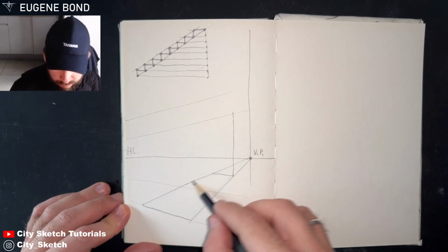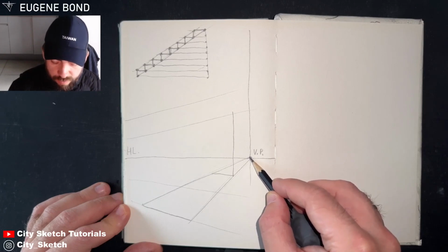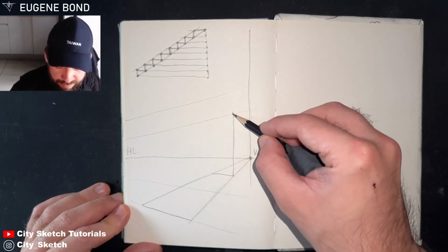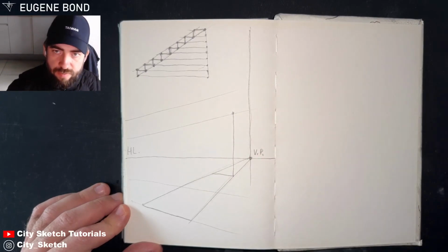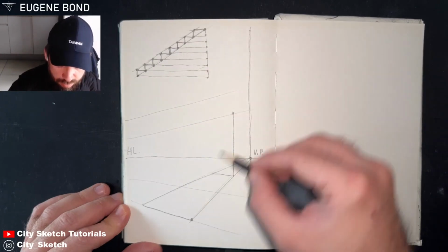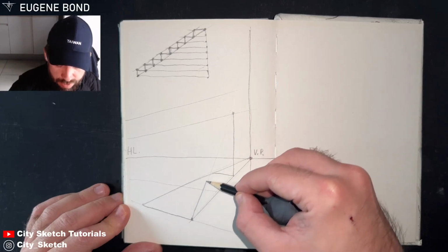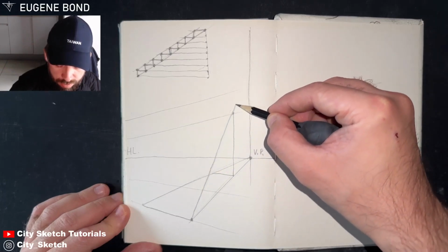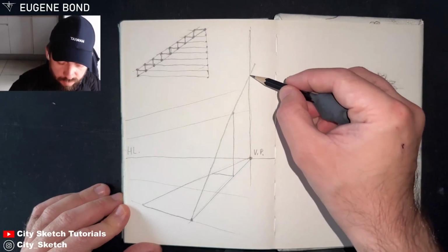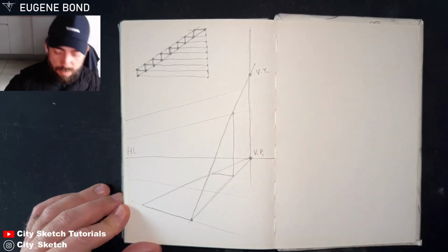So we can see these stairs go to the vanishing point on the horizon line here. And from the same vanishing point, we draw a vertical line. If I want to make these high stairs, and I want to make an uphill kind of direction for the stairs, I connect these two points, and I extend this line until it intersects with this vanishing trace. And we have this vanishing trace point.